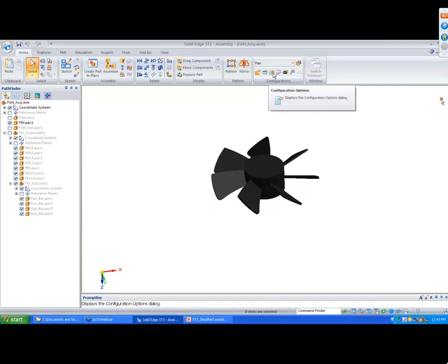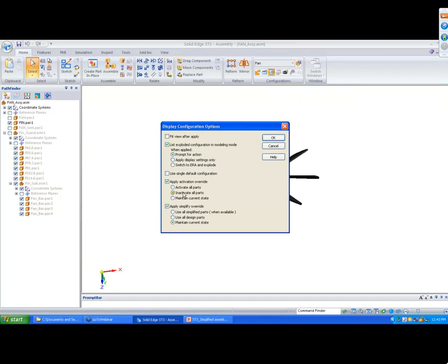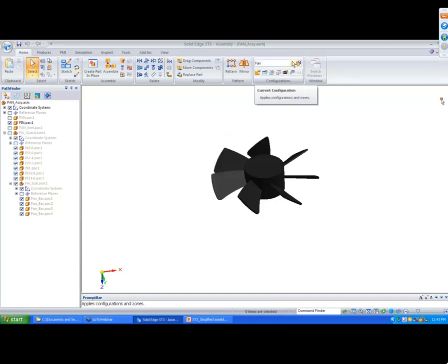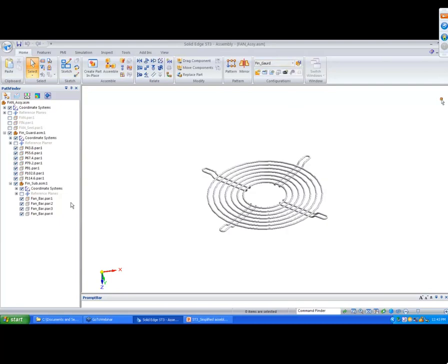By doing this, you can improve the performance. Create an inactivate-all-parts setup, and then if you change the display, it is going to inactivate all the parts. So it's not loading all the math behind the parts into your physical memory. So you can save your physical memory this way.